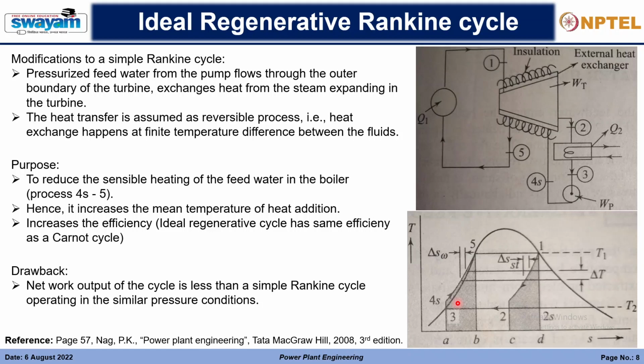Expansion, okay. It will shift to the left, I think; the quality of the steam will be a little bit lesser. For the same temperature, it will shift to the left, because you see this is a constant temperature, and this is a saturated condition. Let us talk about the constant temperature line out here.